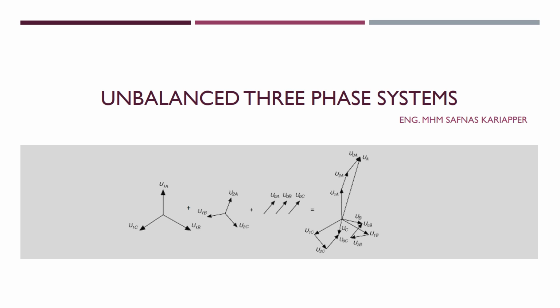And you can see there are some sequence components. Here you can see 1A, 1B and 1C, and you can see 2A, 2C and 2B. So the ABC sequence is the positive sequence, and this one is the negative sequence, because it is ACB. You know this wording of positive sequence and negative sequence already from the last lecture. This other part is normally known as the zero sequence, which you will study.